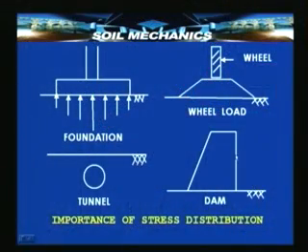This is a typical dam. This imposes stresses on its foundation. The shape of the dam and the water that is stored on one side, all these are going to impose loads on the foundation. The loads are not going to be uniform, and we need to know how the stresses are going to be distributed inside this foundation. As I said, in every one of these instances, ultimately we are interested in knowing whether the stresses which come in the soil are within safe limits or not.